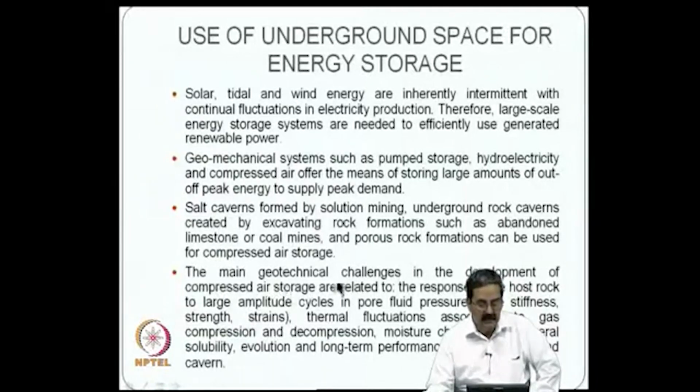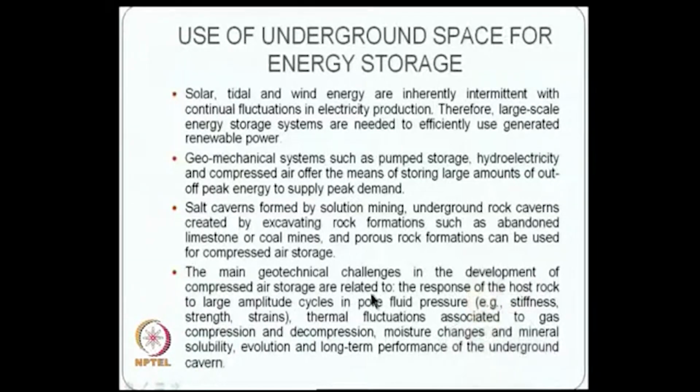So, the main geotechnical challenges in the development of compressed air storage are there. For example, the response of the host rock to large amplitude cycles in pore fluid pressure, stiffness, strength and strains. Actually, what is happening is that compressed air has a lot of pressure inside, and if you store it in a particular material in situ, it exerts a lot of pressure on it. So, the stiffness, strength and strains that are induced because of the compressed air pressure need to be understood in a proper manner.